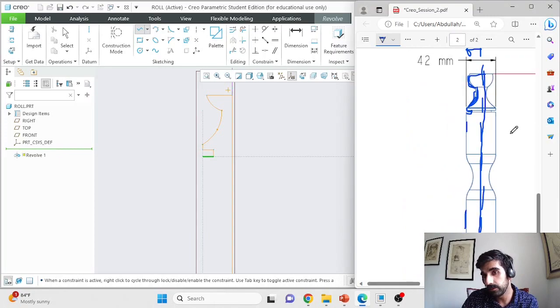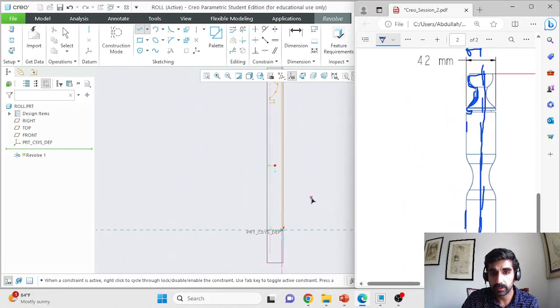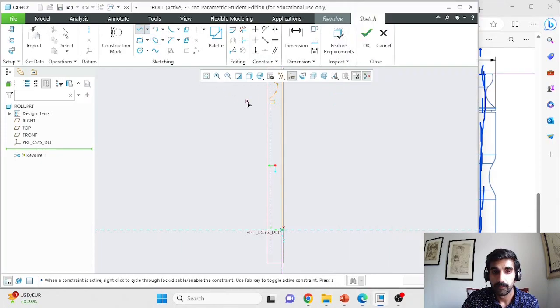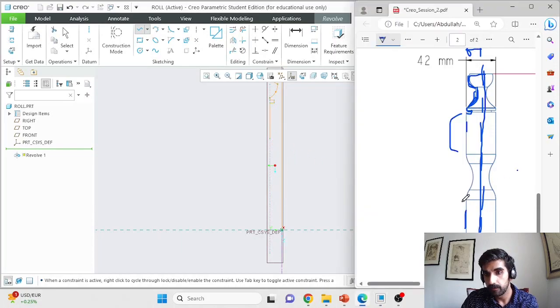Because you are not given very detailed dimensions, you do have the freedom to choose some of the dimensions. So now I'm trying to create this part. So I'll bring this line down over here, press escape, and actually now I'll make this part over here, make the base.